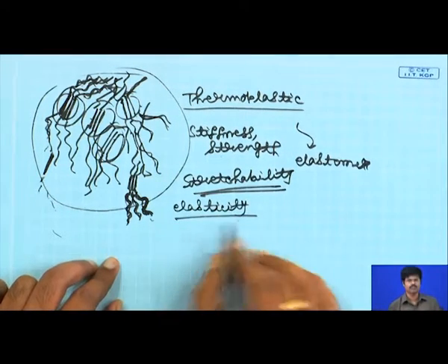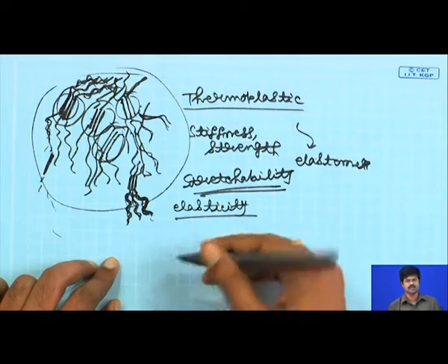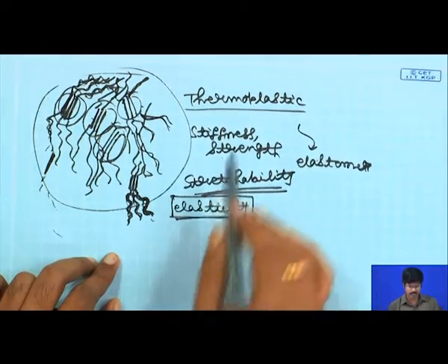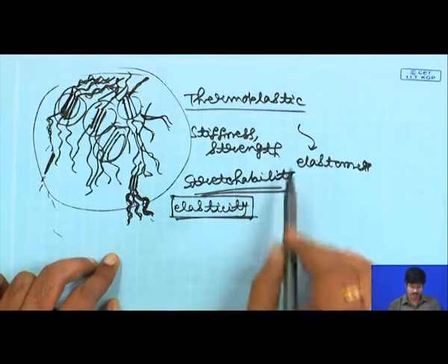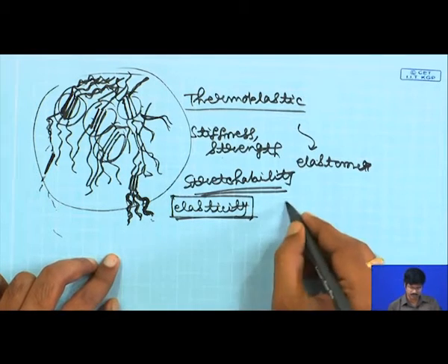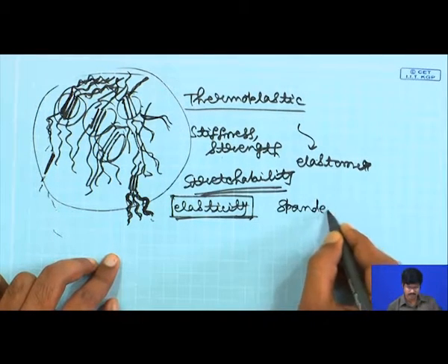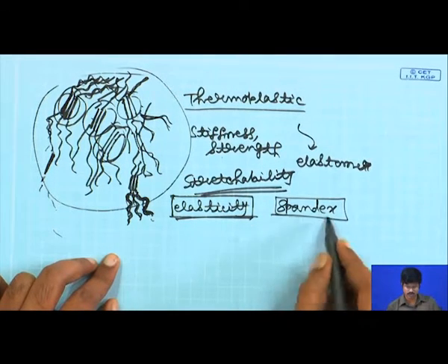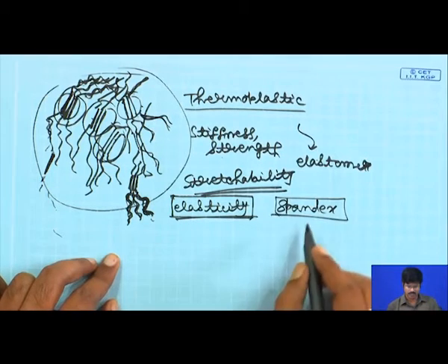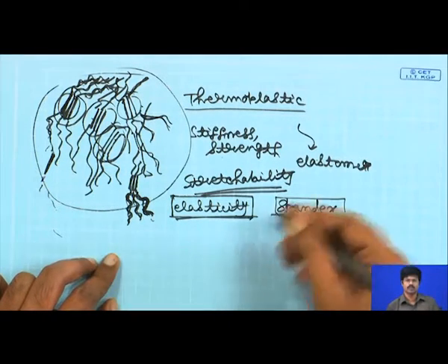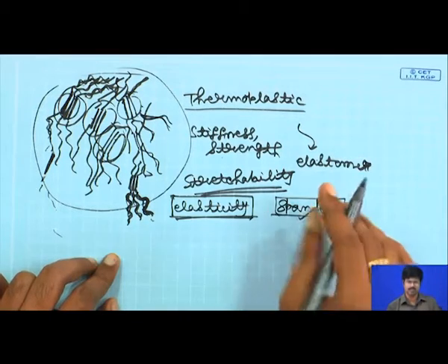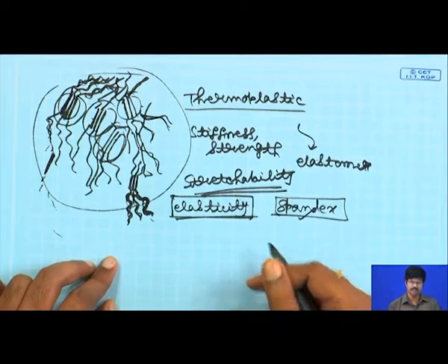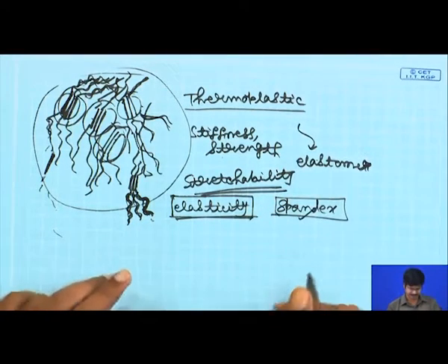It will be non-linear, of course, because your stress versus strain is not linear after, but it will still be elastic. That is why it is called thermoplastic elastomeric material, and as I have already told before, spandex has use in your fabric, in your clothes, especially for sportswear. You will co-spin this particular fiber with your nylons or with your polyesters. So, this also will go into the fabric, that will give the stretchable property to the material that can withstand a lot more wear and tear.